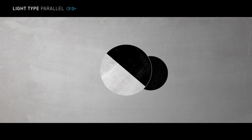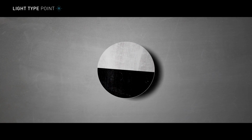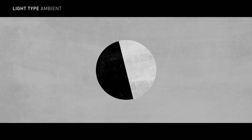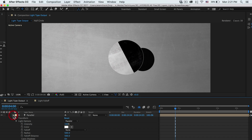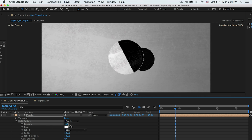Parallel lights emit directional light from a very long distance. Spotlights emit from a cone shape. Point lights emit in all directions. And ambient lights emit with no light source or shadow, but add to the overall luminance of a scene. Each of the 4 light types have options. Intensity is the brightness of the light. Intensity can be both positive and negative, meaning it can add to or take away light from a scene.